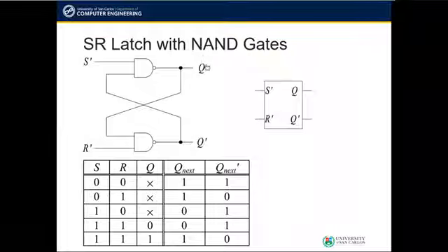This is the Q output and this is the Q prime output. Take note as well of the assignments of the inputs and outputs as they cannot be interchanged. This here represents the block diagram of an SR latch using NAND gates. Let's try to see how the latch behaves using this truth table. Let's examine its behavior according to each input-output combination.